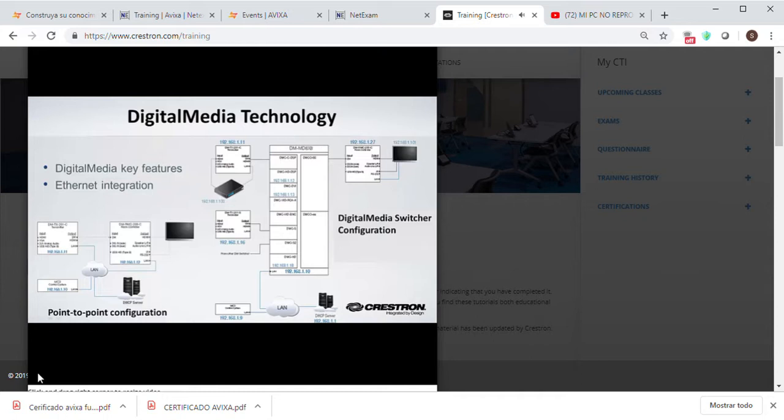Some Digital Media transmitters and receivers come with a local area network port, so in a scenario where the room box is connected to a DM switcher, this port can be used for connecting other Ethernet devices. In a point-to-point scenario, the Ethernet port can be used as an uplink to the main network.